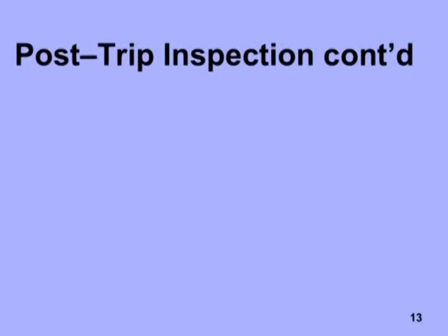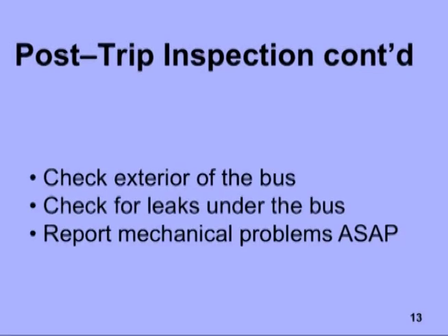Continuing with the post-trip inspection. Walk around the exterior of the bus to determine if there are any changes to the bus or at the parking location. Check for leaks under the bus, specifically for oil, antifreeze, and transmission fluid leaks. Report any mechanical problems as soon as possible through verbal and written reports.